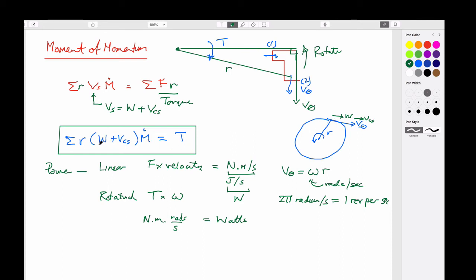And so you have to remember that the components of these velocities are that this is squirting out of the hole in the sprinkler, and this has to be in the same direction. So if the rotation speed is actually going in the direction of this arrow, then this would be negative, right, in this term here. And so there's a sign convention to remember. All right?